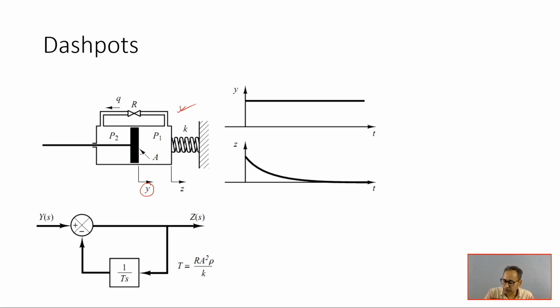to the piston, this is the power piston, this is the cylinder. If you give this displacement y to the dashpot piston, then there will be a momentary change of the displacement. See, this cylinder is not fixed; the spring is fixed on the other side, and the cylinder is attached to the spring at one end. So when you give some displacement y, this end point of the cylinder will also experience some displacement z which is equal to y.